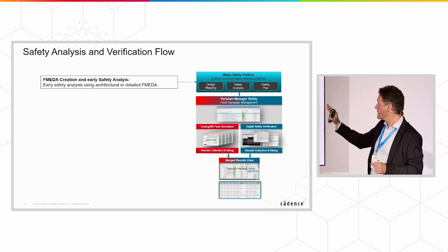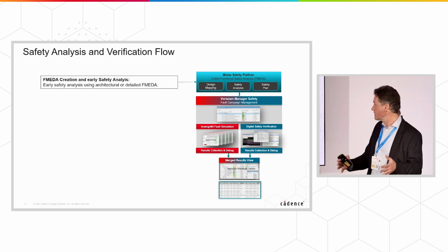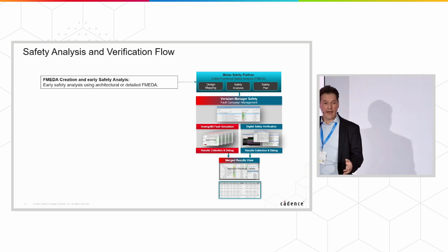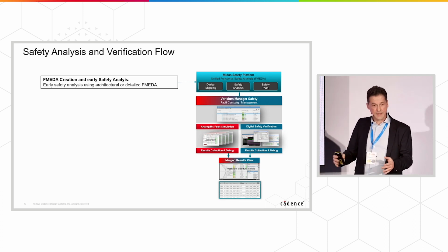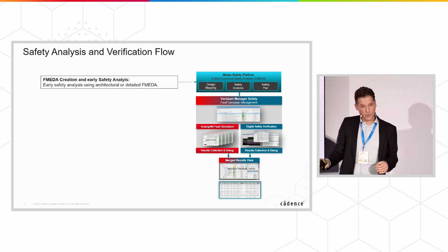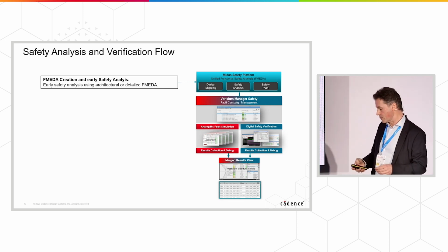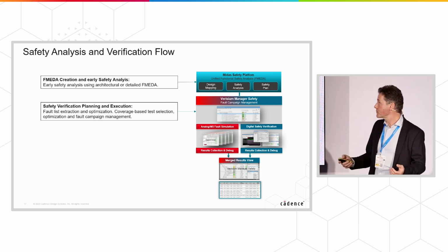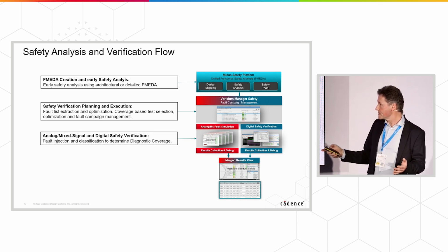So we have MIDAS sitting at the top. And the next tool in the flow is now the Verisium Manager Safety, which is driving and automating the safety verification flow. Underneath Verisium, you can have either an analog mixed signal safety verification of your design or a pure digital safety verification of your design, or a mix. At the end, once you're done with your safety verification, you create a merged results view out of Verisium. And you can also generate reports that are showing the coverage, the verification coverage of your design. So that means Verisium is the tool to set up your safety verification and execute the verification, also optimize your tests and so forth.